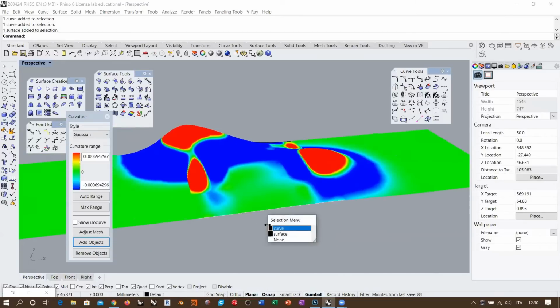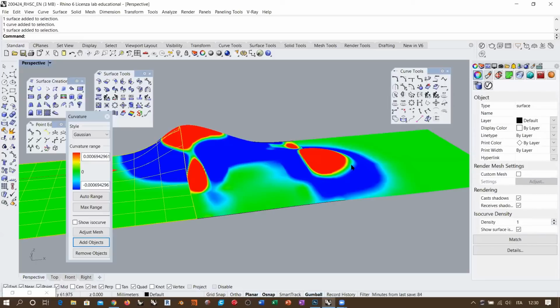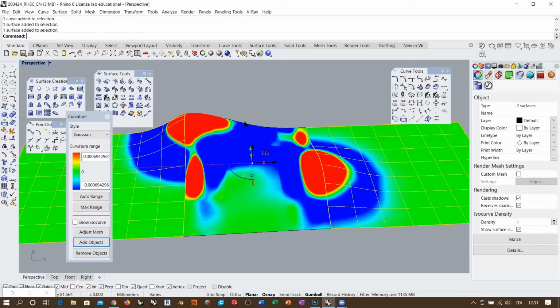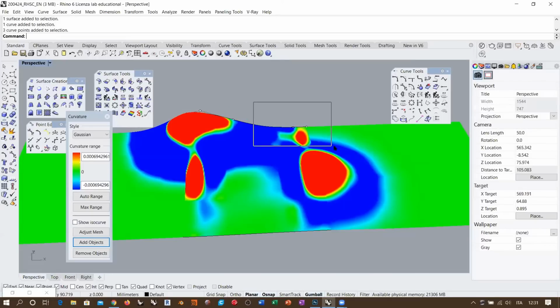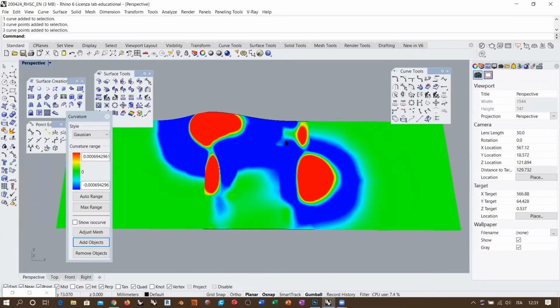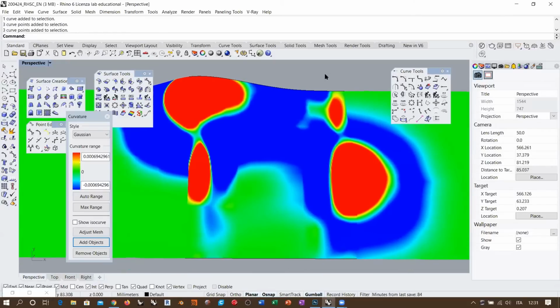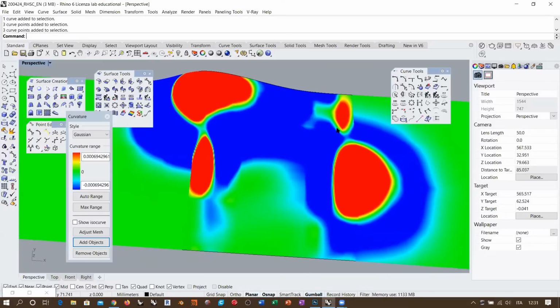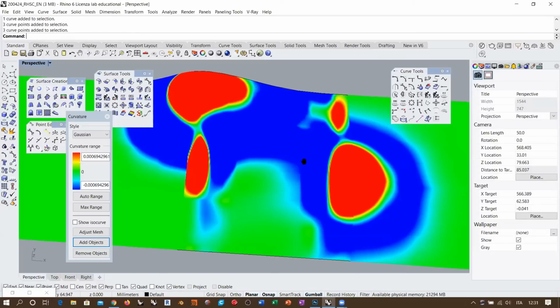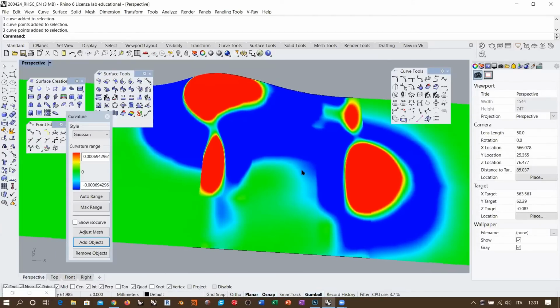Of course, you have to adjust the continuity between this curve and the adjacent surfaces, not taking tangency, tangency like we did here. We adjusted to curvature, curvature. So you see that it's a complex set of considerations when you create this kind of surface. It's not just what's the best process. It depends on what you want to achieve, what's the importance of the input curve that you are using, how important it is to have a smoother aspect or a complex topology. It depends on many considerations, Tiziano. It's not a single answer for all.